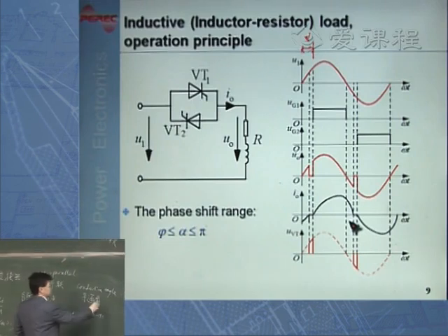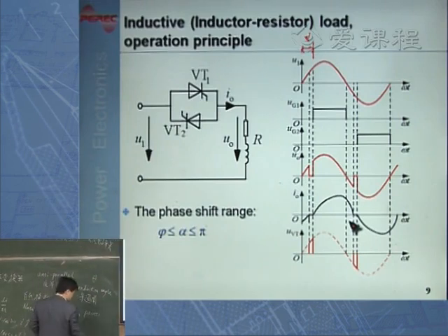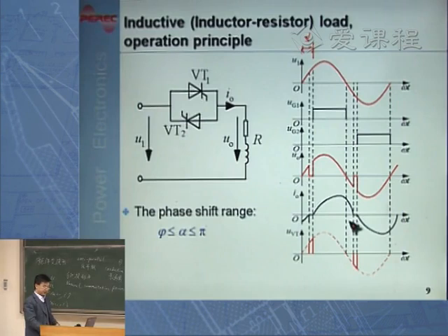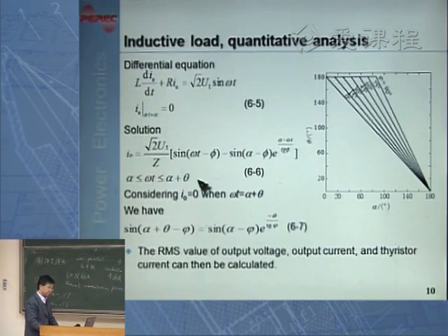And we usually use theta to represent conduction angle. So you can figure out under different situations how much this conduction angle is. And you can figure out that based on this equation, this conduction angle will be depending on alpha, the triggering delay angle. It will also be depending on another thing, phi. What is phi?